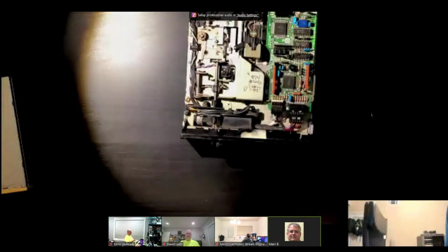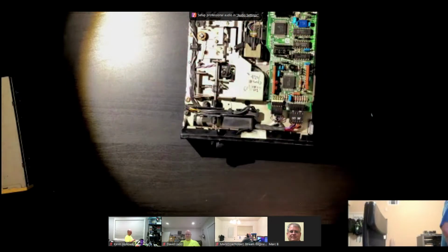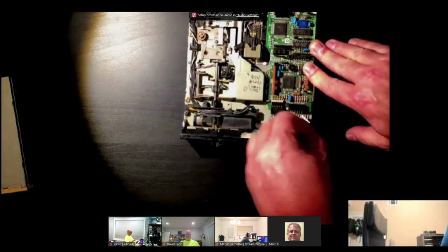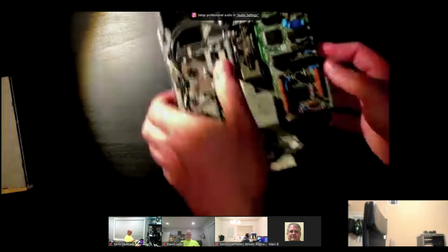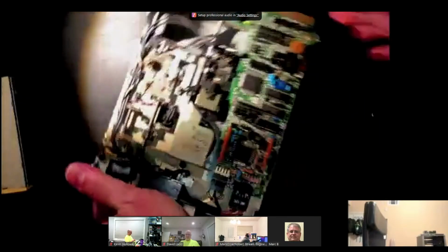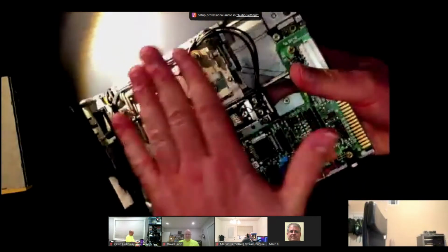And of course, take it apart, clean everything. And this drive, I broke it by turning this connector around because I was futzing around. This was a freebie. This particular drive here was free from the VCF West pile, so I didn't mind breaking it. Plus, it's a 1.2, and I have a bunch in the box. So that's the maintenance that you need to do on any drive that you want to use for imaging.